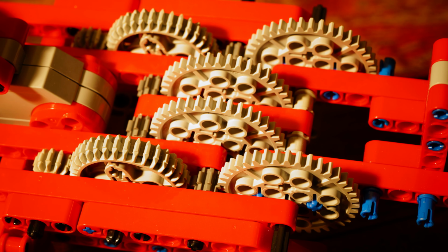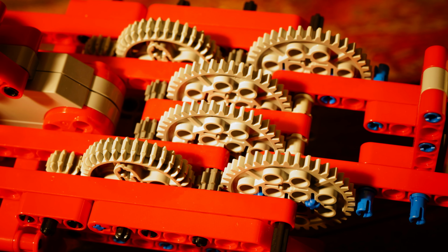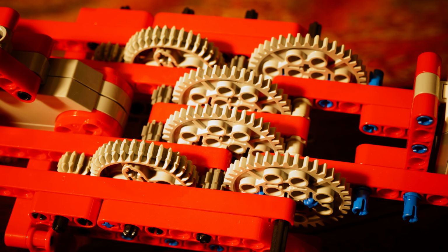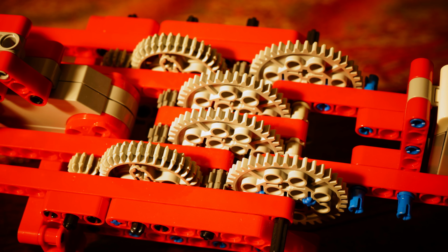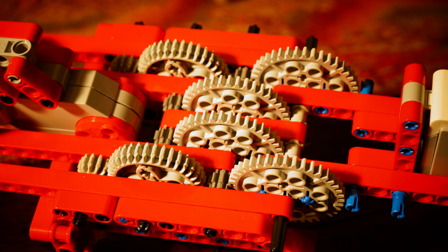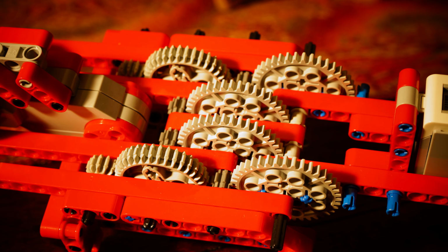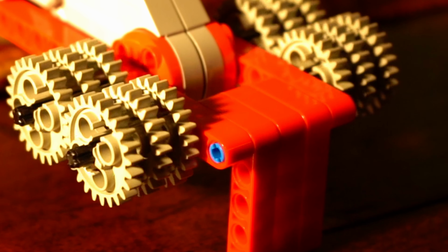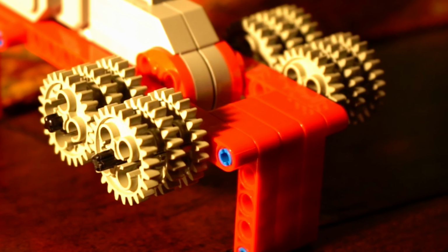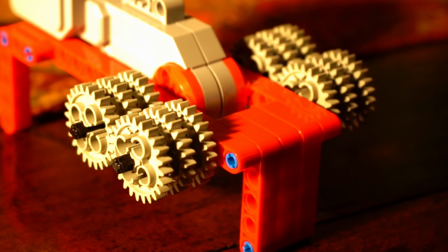However, each of the outer axles, despite having only a single gear size, is also a compound gear because two gears appear on each axle. Thus, both driver and driven gears can also be compound gears. For example, these two compound gears each comprise six 24-tooth spur gears turning in unison.